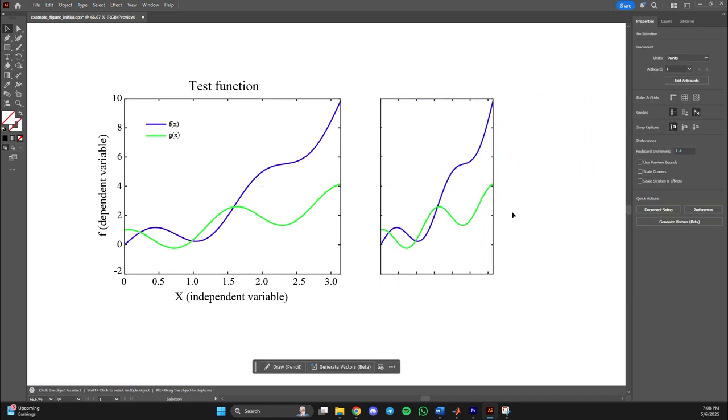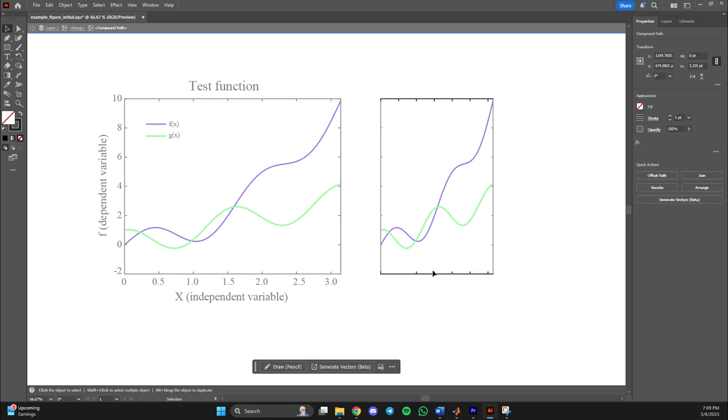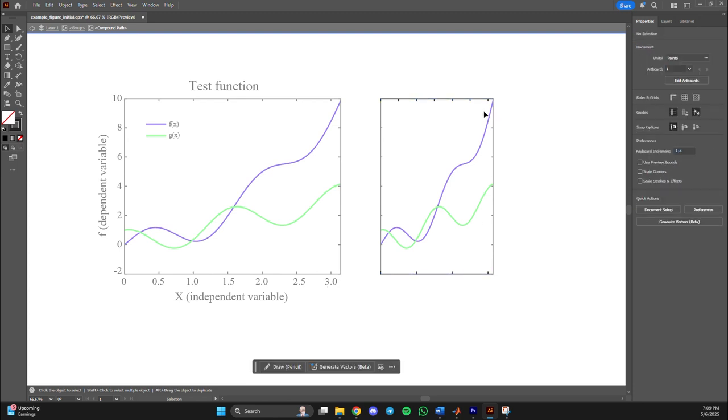Here we can position it to the right, for example, and we can play with the aspect ratio of the curve. As you may imagine, if we have too many ticks on the horizontal axis and we compress the figure in a more vertical display, we may want to remove some of the exceeding ticks. To do so, we just enter our group. We double click again to enter the group corresponding to the axes, and we can remove the intermediate ticks as desired.